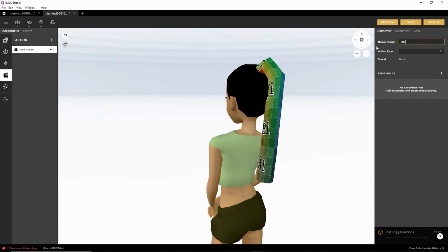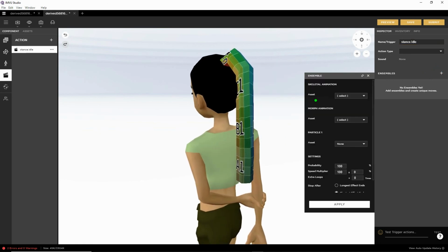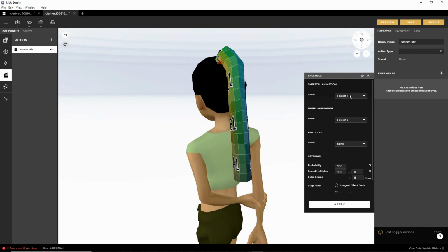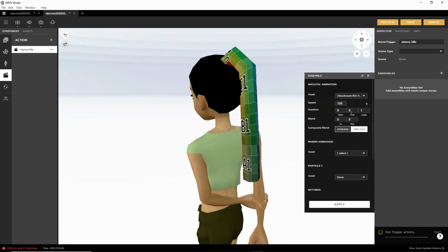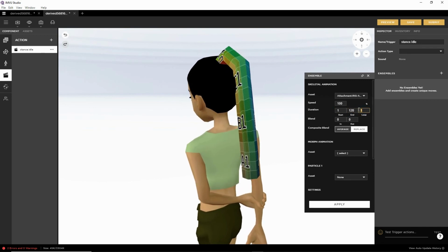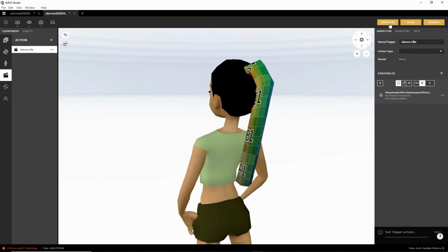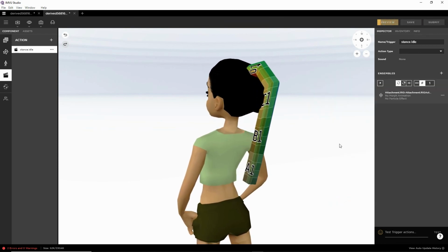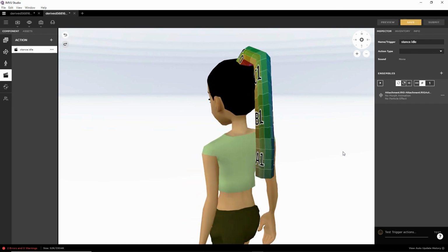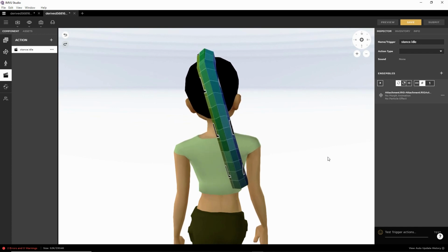Again, starts.idle, because we want this to play all the time, and it's case sensitive. New ensemble, asset. There's our sequence. Set the frame range 1 to 120. Number of times it loops 0 for infinite. Replace. Everything else is okay. Apply. And then preview. And there is our animated accessory item.